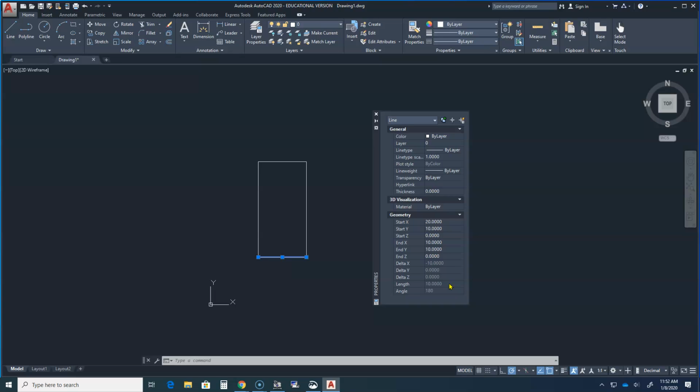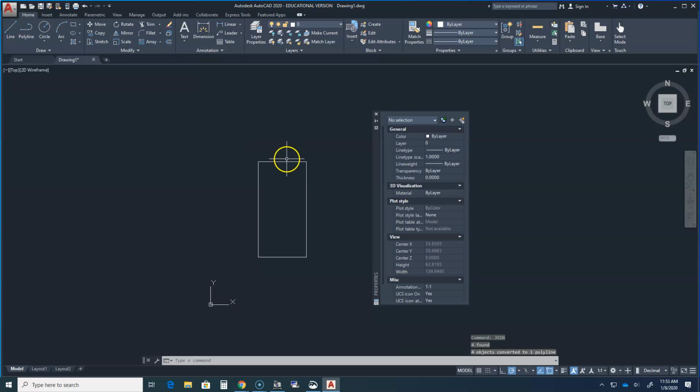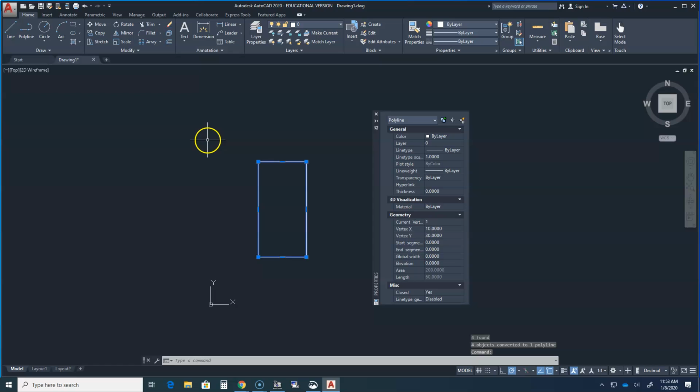However, that may not always be the most accurate way to do it, and it's definitely not the quickest way to do it. So what I'm going to do is click and then hover over the entire rectangle, and then I'm going to type the word join. So now this is all one entity. Okay, it's one shape. It's basically like one line going all the way around, joining from one end to the other. And now I can look in the length area, and you see I get a different figure, and this would be the total length of all the lines included to make that shape.